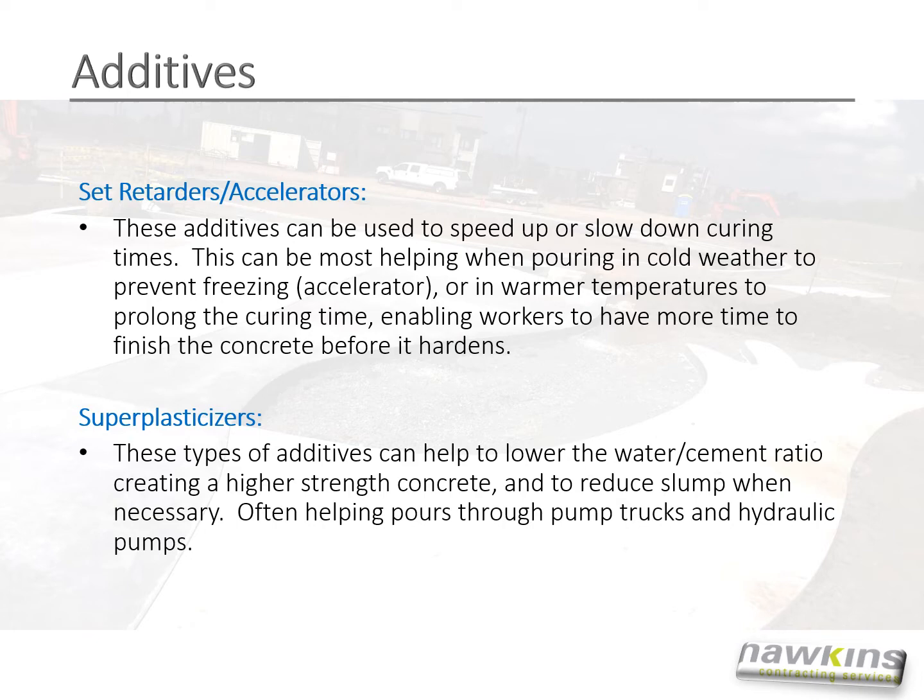Superplasticizers. These types of additives can help to lower the water-cement ratio, creating a higher strength concrete, and to reduce slump when necessary, often helping pours through pump trucks and hydraulic pumps.